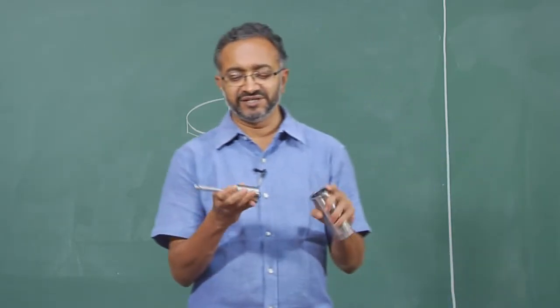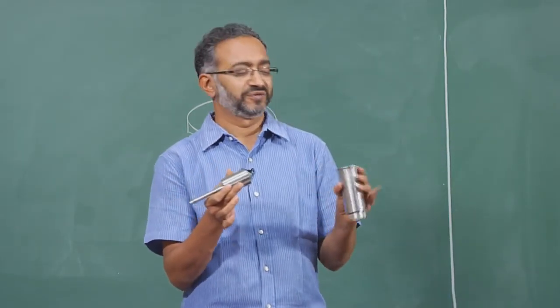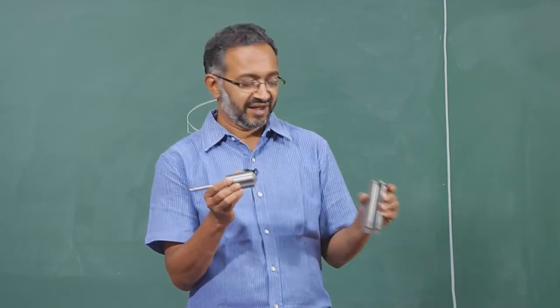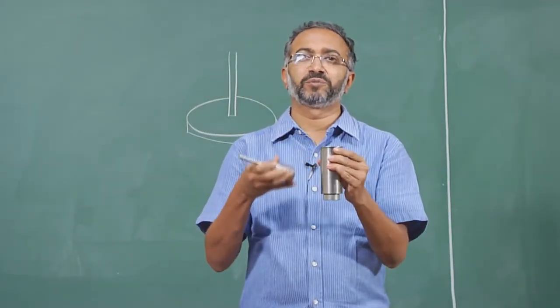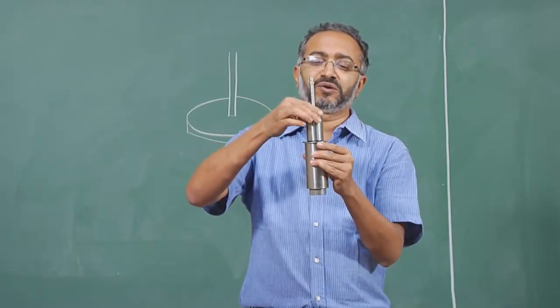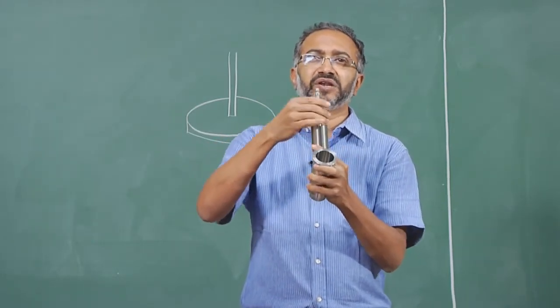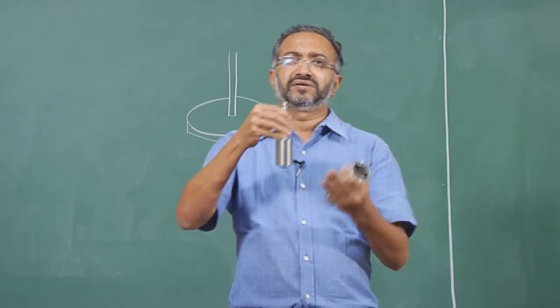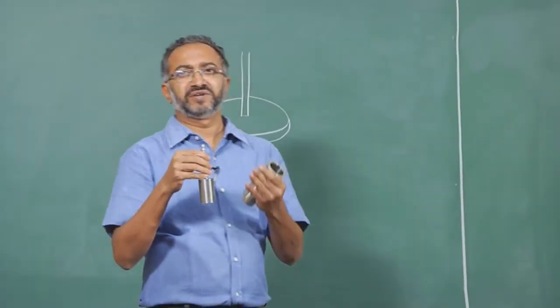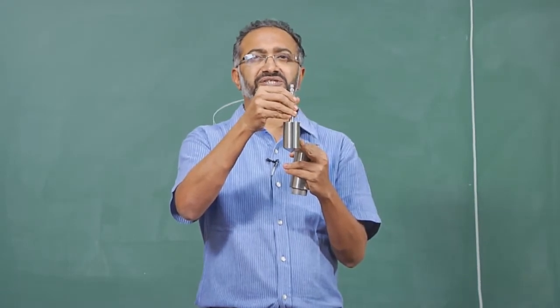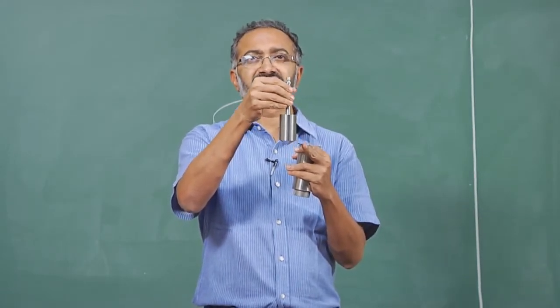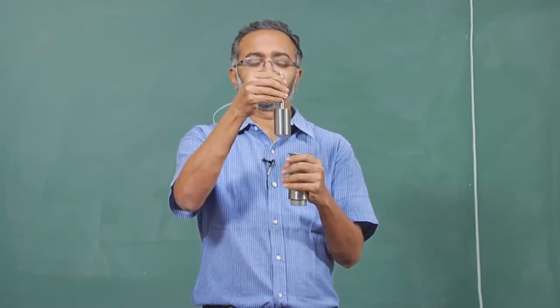And the question then is, why is this useful for low viscosity fluids? This is the cup in which the sample would be taken, and then this bob would be lowered, and then the bob will do the rheological experiment that we would prescribe. For example, we may do an oscillatory shear, in which case the bob will basically go back and forth.